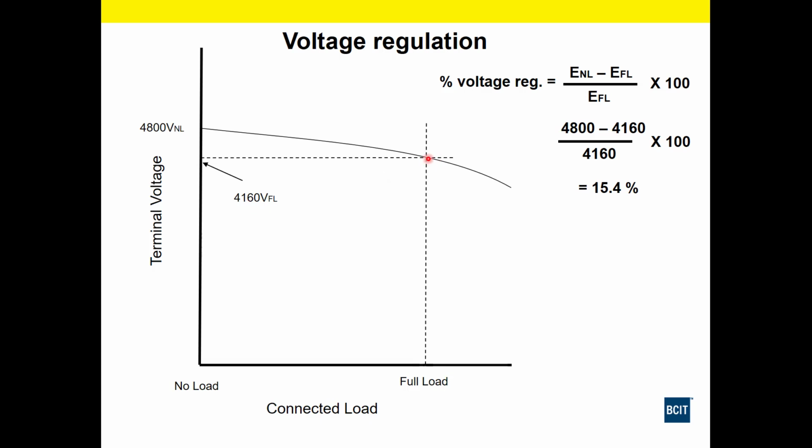Now sometimes we're going to operate it higher, because BC Hydro's alternators might have to transmit electricity a long distance without going through transformers, so they might take the voltage drop of the lines into account and overexcite their field in the rotor circuit to overproduce the voltage, so we can have a reasonable voltage level by the time it gets to the end of the lines. That's if there's no transformers, but BC Hydro is going to step their voltages up to 500 kV and send it down the length of BC to the Lower Mainland from up in the Peace Country.